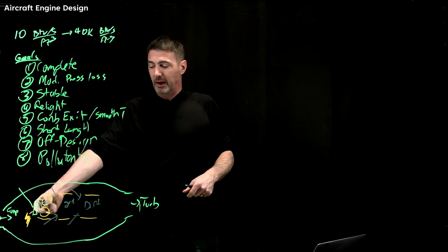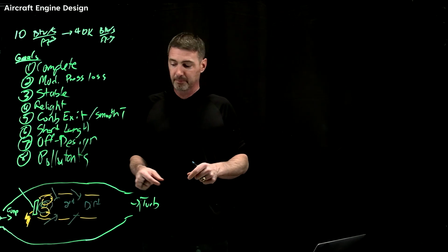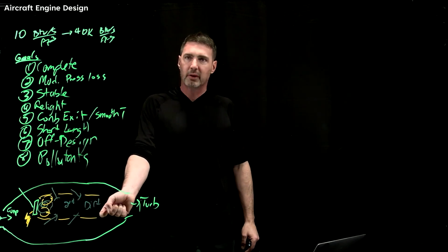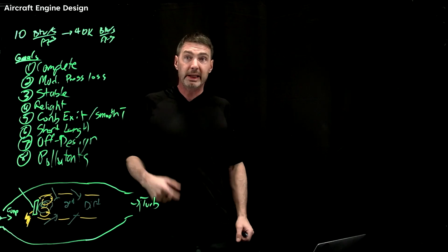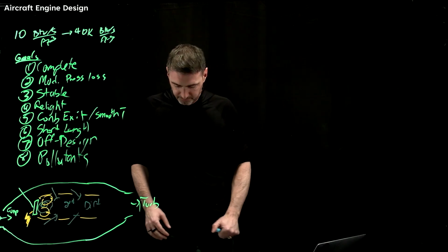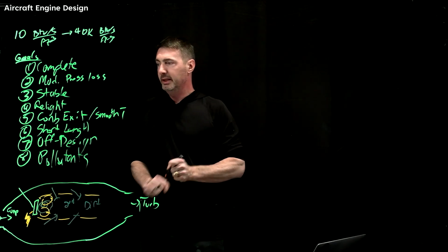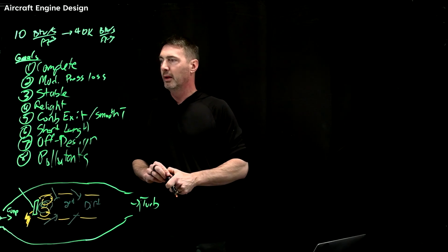So you have coolant air going across, but also coming through the holes, starting to dilute that flame a little bit, and then ultimately quenching lean here for emissions. So fuel-rich for stability, quench lean for emissions. Yeah, we talked about these. Where did it go? Complete combustion.